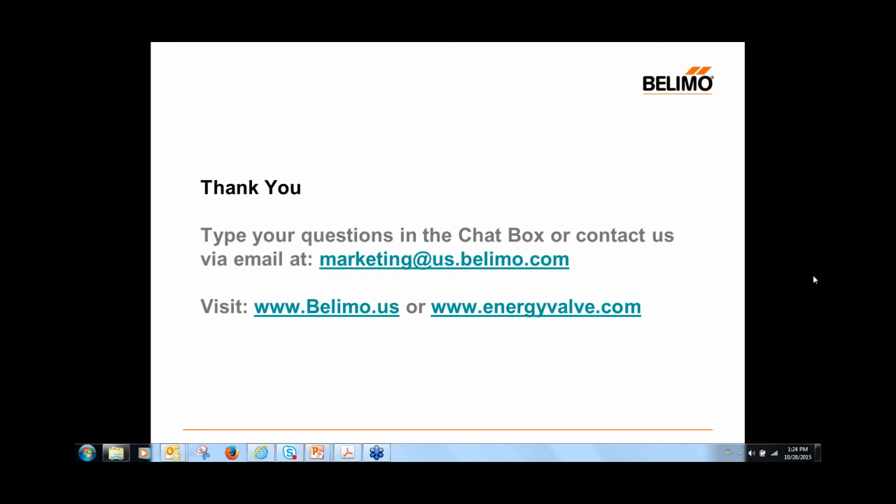Couple more questions coming through. Does the energy valve provide any alarms? For example, if a coil is fouled or a sensor is not functioning properly. Yes, it does. All the diagnostics we saw on the status page can be exported as BACnet alarms.